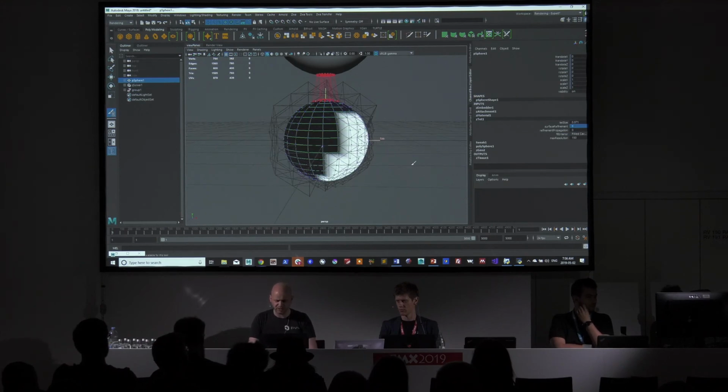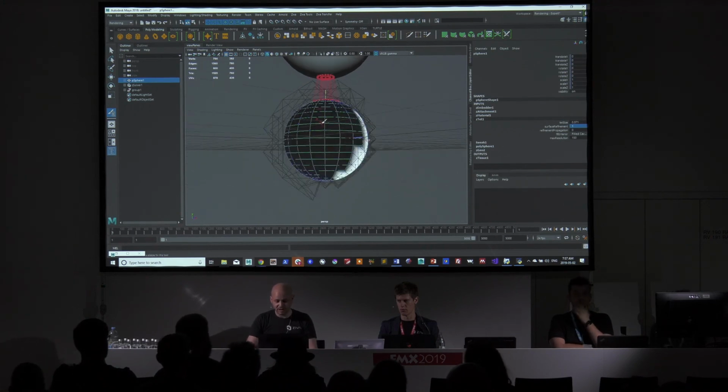And also, one other thing, in case it wasn't clear earlier, the resolution of the TET mesh really just has to be the right resolution to contain the deformation and the oscillations that you want. So a lot of times you can get away with really coarse TET meshes for things like muscles because they just squish and bulge. You don't normally see waves run up and down muscles unless you're doing high-speed photography. So you can get away with coarse TET meshing. All of the collisions, attachments, all those forces are applied at the surface that's embedded and get propagated out to the TET mesh. So you can decouple the concept of the resolution from how things are set.